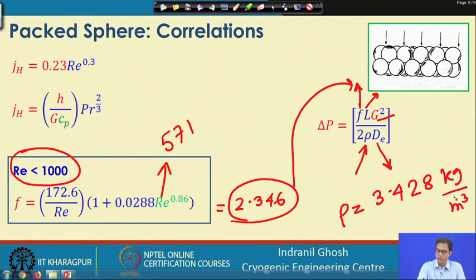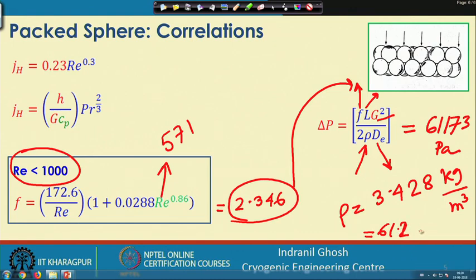If we put all these values in this relation, we find that this comes out to be 61173 Pa, which is equivalent to 61.2 kPa. So, we can estimate the pressure drop for this packed bed for the given flow rate, which was 0.08 kg per second. We find that the estimated pressure drop is 61.2 kPa.